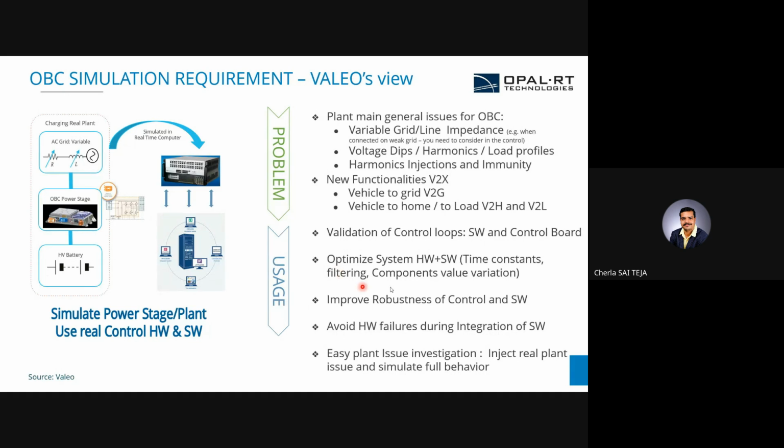So here the component value variation is whenever the pulse is high and the switch is closed, you want to open the switch at that instant. What we can do, we can create a scenario wherein during the on time, we'll make the resistance very high, so that even though the pulse is high, the switch will be open, or vice versa.